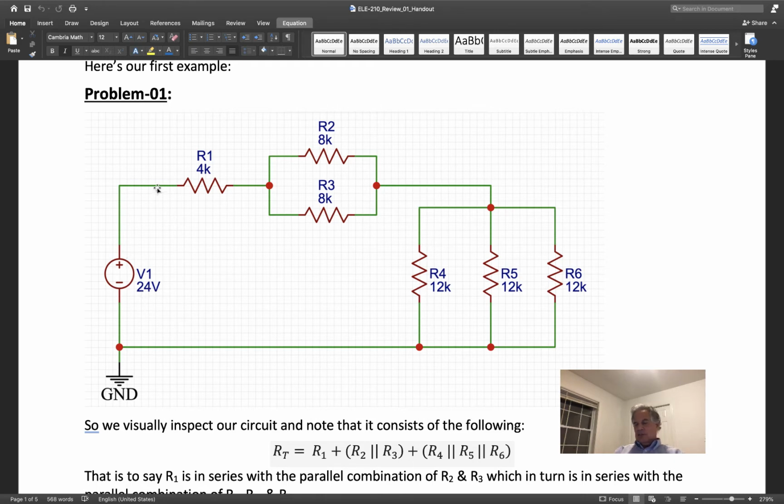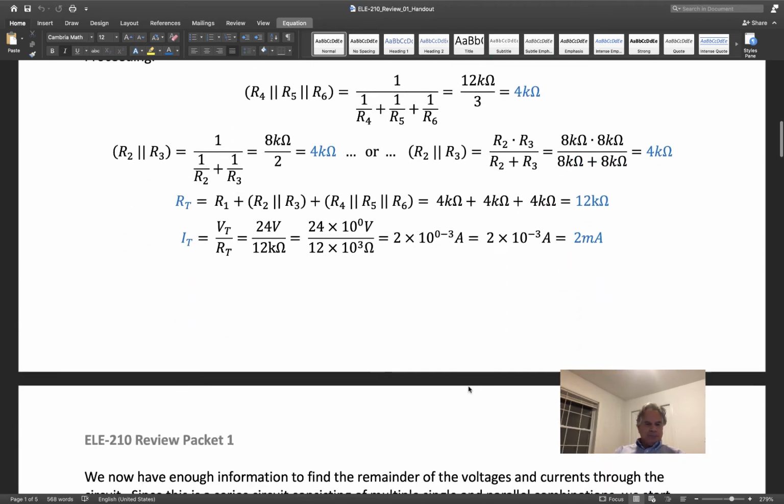Then we add our voltage drops. We get a plus 8, that takes us to minus 16. Another plus 8 takes us to minus 8. Another plus 8 takes us to 0. We've finished the loop, and we came up with 0 as a total of the voltage rises and voltage drops around this loop, which satisfies Kirchhoff's voltage law, or KVL.